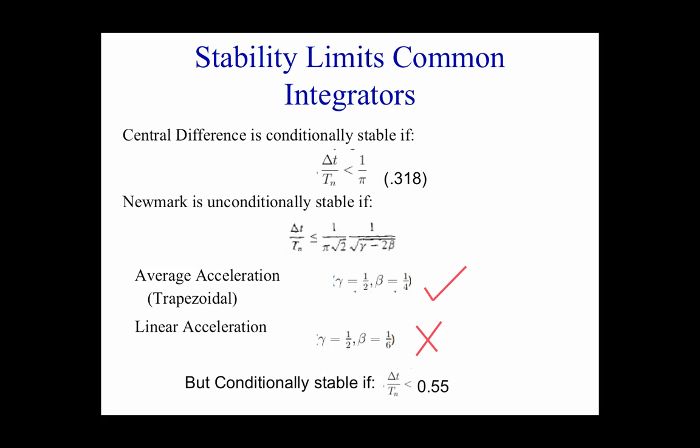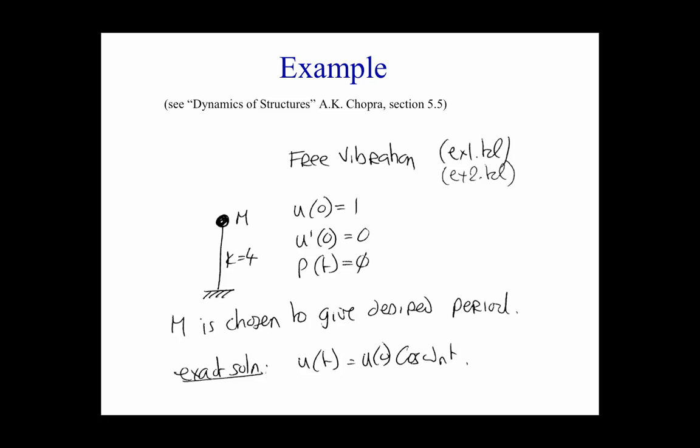No, in OpenSees you specify delta T in the analysis. I don't know what the period is. I don't ask the structure for all the different periods. I don't know what periods you're worried about. How do you make the decision? Well, that's the modeling thing, right? Again, as I say, most people just take the delta T from the earthquake and they run it through, and that's it. Right? They don't think about, well, what are the periods in my structure? What impact might they have? And because they get answers at the end, they're done. Right?